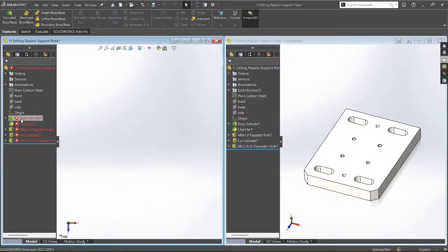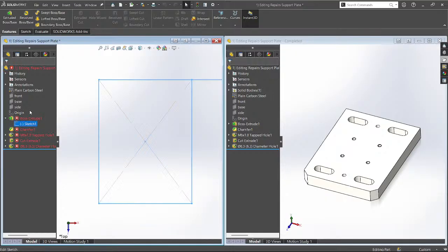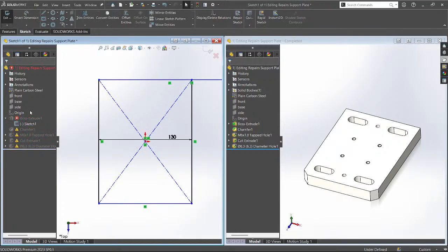So I could see the first error here. It is showing the sketch contains an open contour in chart. Okay, so sketch has the open contours. I need to resolve it. The error is related to the sketch in chart, so you can use the drop down, right click, edit the sketch. Now simply try to run the repair sketch and see if there are any issues. If there is nothing, just leave it.